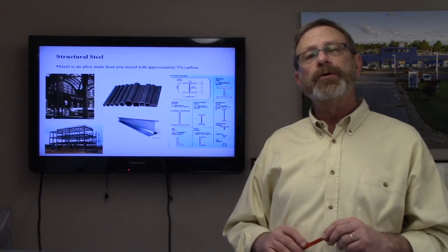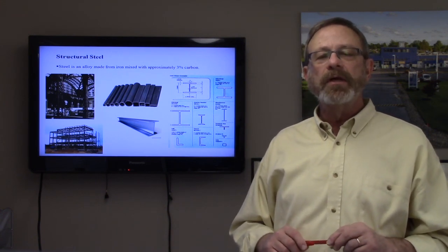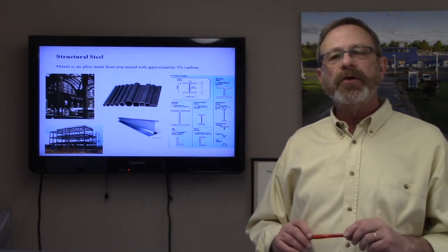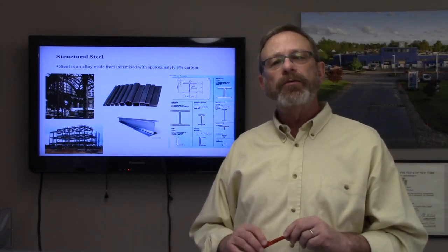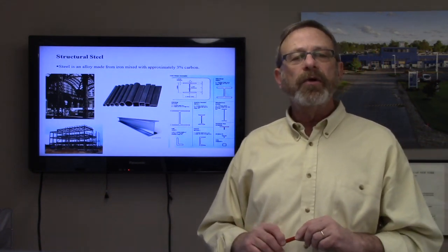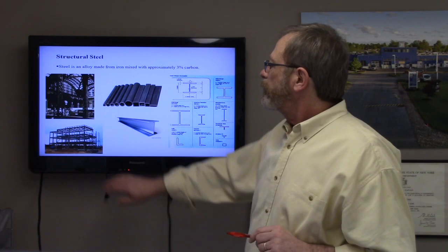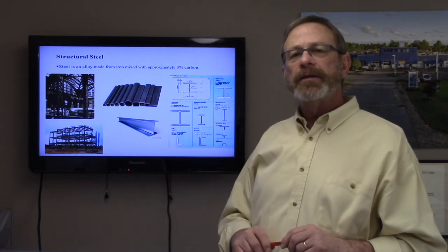So at normal temperatures, steel is very strong, but if a fire develops in a steel frame building, the columns and beams, even if they're covered with fire insulating material, may get hot, and if the temperatures rise above 700 degrees Fahrenheit, will lose their strength. Here's a steel building. This building no longer exists. It's the Penn Station building that was taken down in the 1960s.